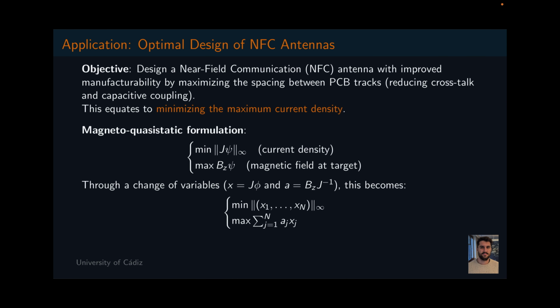Now, let's transition from abstract Banach spaces and see why this pure mathematics deeply matters in the real physical world. We applied our analytical solution directly to the design of near-field communication, or NFC, antennas. In standard PCB manufacturing, tightly packed antenna tracks are a nightmare. They cause unwanted capacitive coupling, signal crosstalk, and manufacturing errors that lead to short circuits.